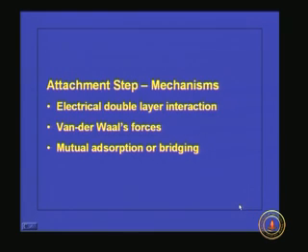Once again, we will see the different transport phenomena. One is mechanical straining. We have seen how it happens: in between the filter media there are pores. If the pore size is smaller than the particle diameter, naturally the particle will be removed, and with respect to time the pore size gets smaller and smaller. So, more and more finer particles get removed.